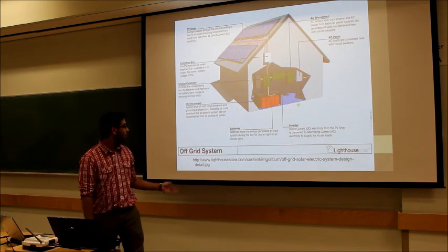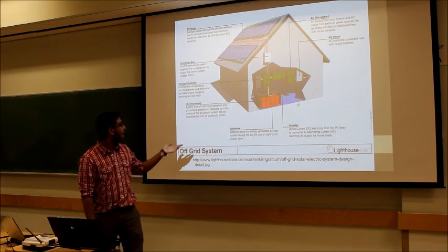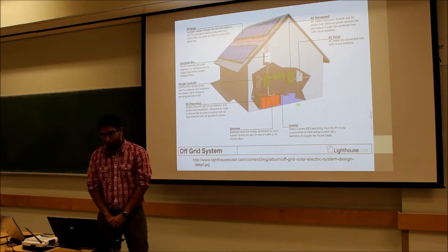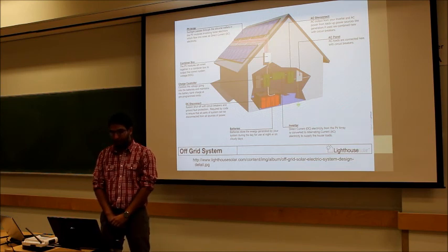As you can see here, an off-grid system has been shown. The charge control limits the rate at which electric current is either added or drawn from the batteries, thereby preventing overcharging and deep charging that can impact the batteries' lifespan.